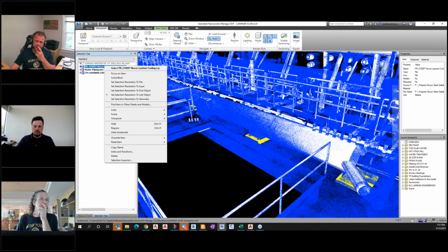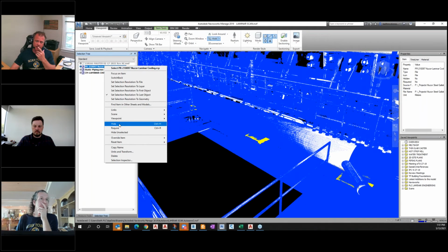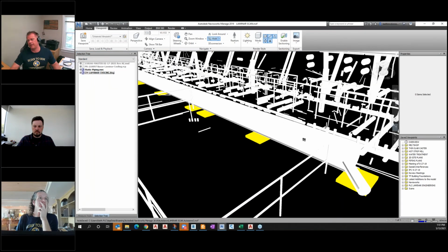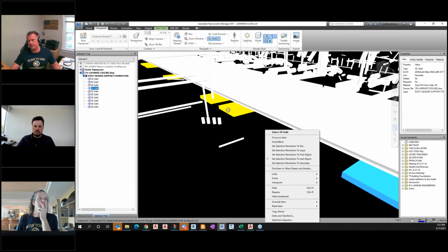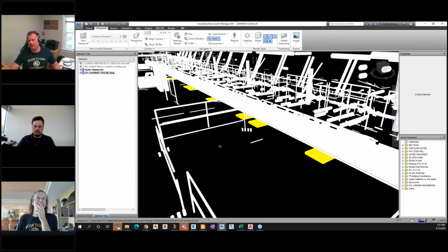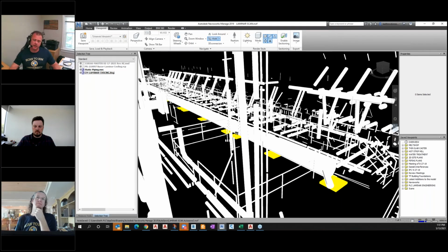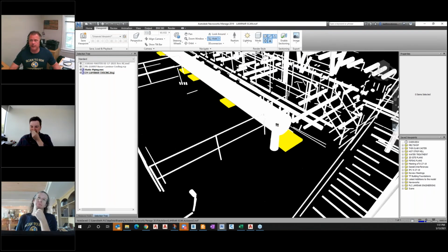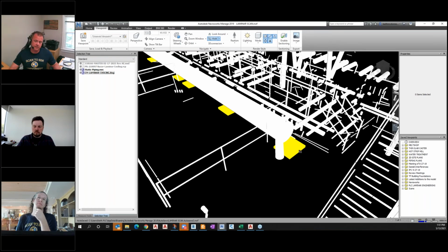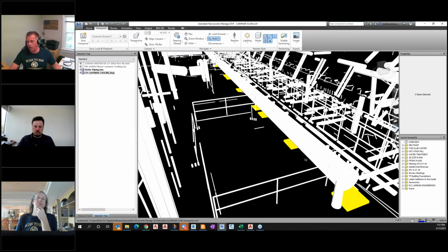So what I'm doing here is, although all this equipment's getting torn out, I've scanned it all, and then I've gone in and started plotting out all the existing foundations, because I want to see what I can leave in place post shutdown while I'm doing the new work. The next step is to start designing my new foundations for the new piping. Then I'm going to try to work around these so I don't have to tear them all out. The less work I have to do during that window, the better.